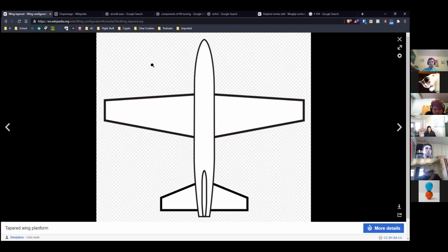And all the factors in an airfoil, the reason you can just apply them to any wing, is that they're dependent on the chord. For a wing slice of any chord, because an airfoil is just a cross section, that chord dimension will define all the rest of the parameters. The airfoil just contains the function that turns the chord into each of those parameters.